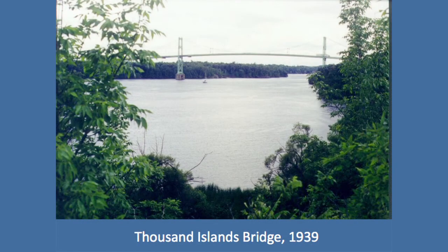Well, the cables of the Roebling, the diagonal stay cables, have already been dismissed as unnecessary. The truss, the stiffening, has been dismissed because the George Washington Bridge didn't have them. Now you've got a very light bridge, and what happens? When the wind blows in certain ways, the roadway of this bridge undulates. And this took engineers by surprise in the late 1930s.